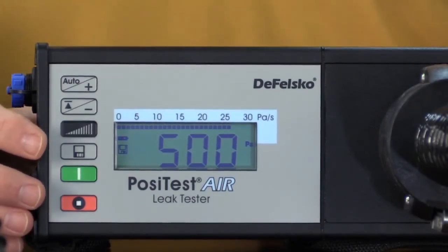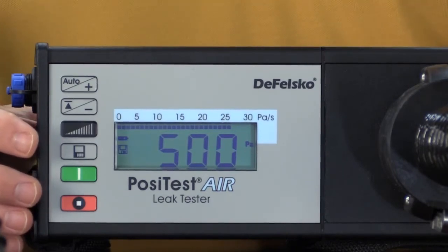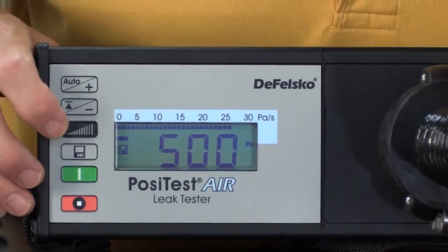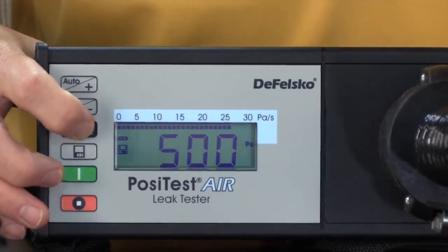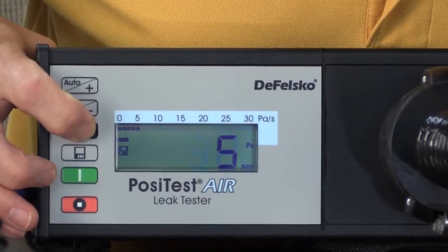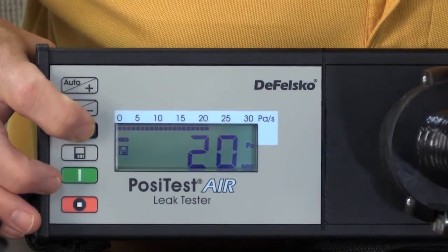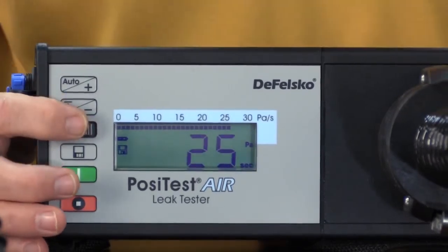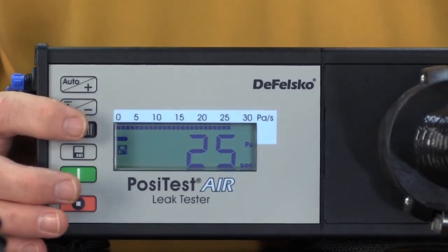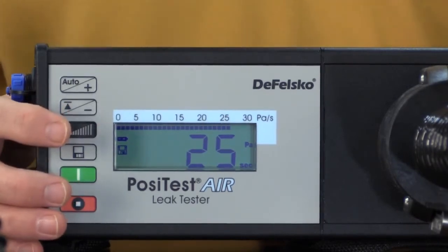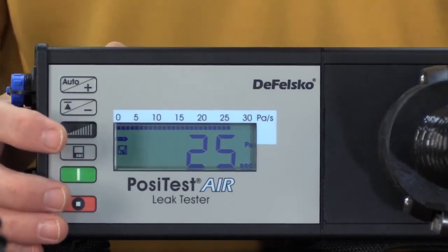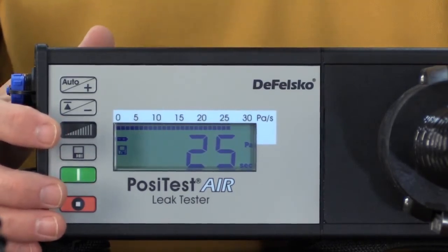The pressure differential is created by adjusting the fan speed. That's what pushing that button does. The rate of depressurization is adjusted by pushing this button. It changes the rate in increments of 5 pascals per second, and the common setting here is 25. We recommend the use of the auto mode, particularly when starting up. If you don't use auto, then you have to adjust the pressure differential manually and the rate of depressurization manually as the test is being accomplished.